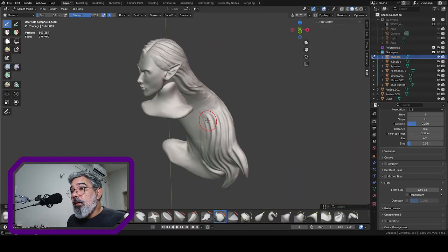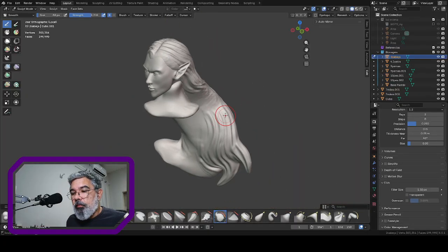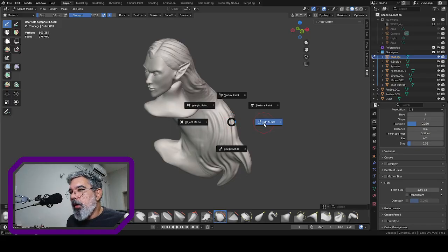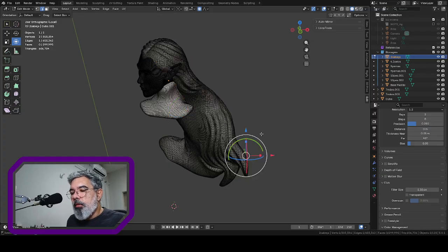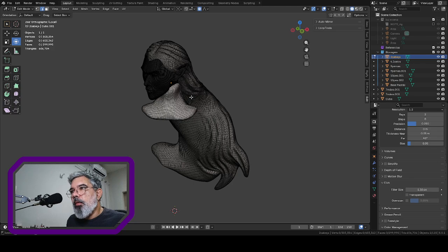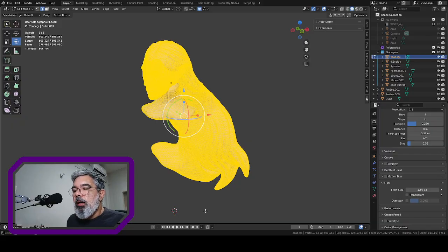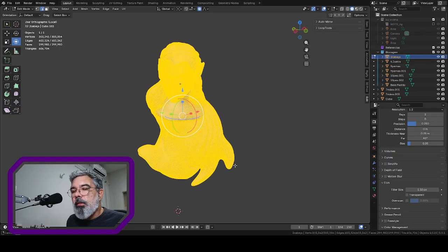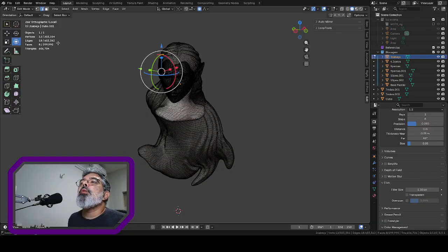Okay, from time to time you need to do a process. You must come to edit mode. You need to select just the Boolean meshes that are already done, and then come to edit mode. You click in any empty space, put the mouse on the model, and press L on your keyboard to select all the visible vertices, and then press Ctrl I to invert. As you can see here, we have 12 vertices that are inside the model, and you just grab them out.